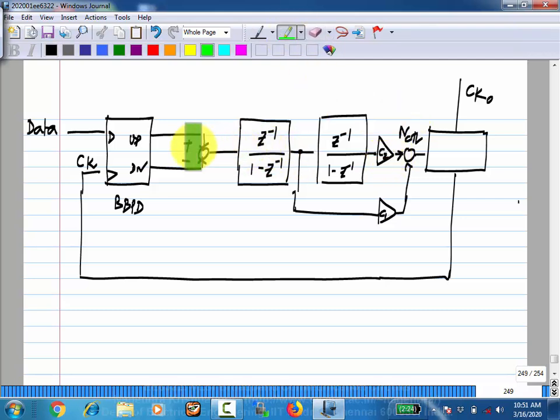So hopefully this is the part we had, only the first part, right? First integrator we had for the case with the forwarded clock. For the second one, now if you have a constant phase difference, you will keep getting some constant signal here, right? And based on that, you give a ramp so that the frequency gets corrected. That's the idea. Okay. So now you can also make this exactly same as the analog CDR. I could have derived this from scratch, but since we had already done that, I thought we'll use the phase model of that to derive it. Okay. Hopefully the part without the forwarded clock was very clear, and based on that you can calculate it.